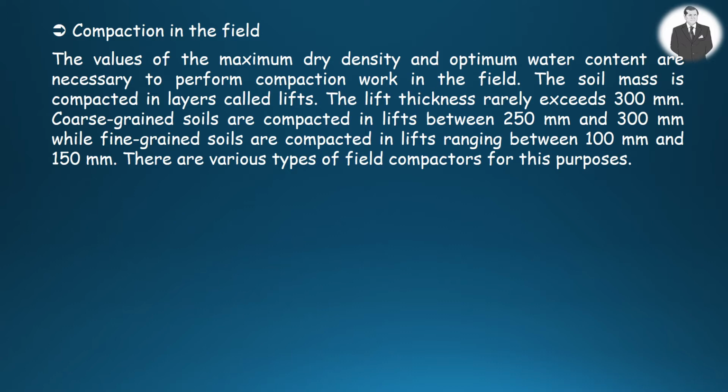As the coarse-grained soils are compacted in lifts between 250 millimeter and 300 millimeter, fine-grained soils are compacted in lifts ranging from 100 millimeter to 150 millimeter.